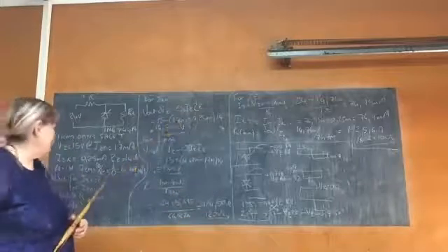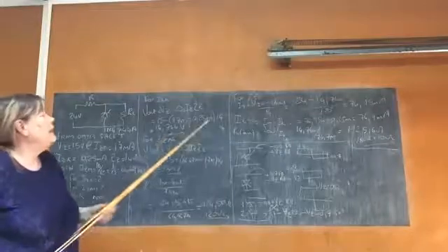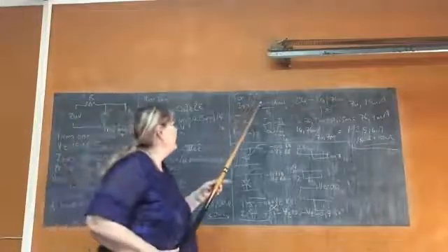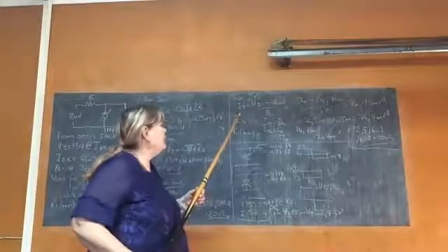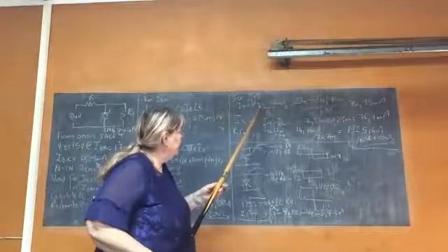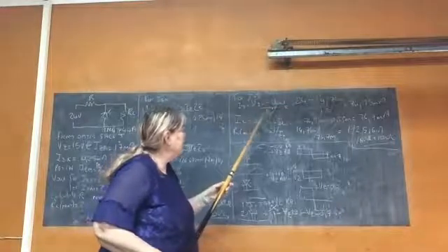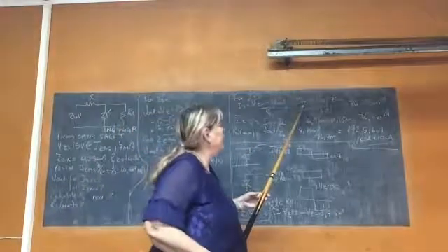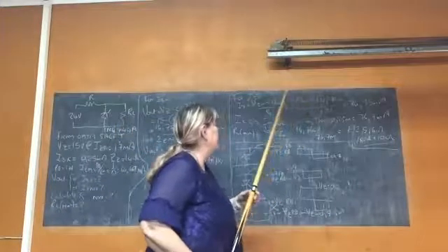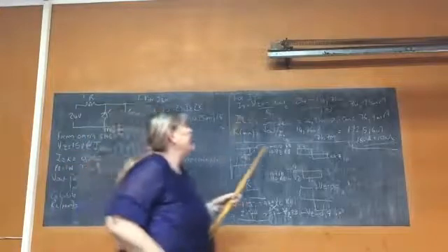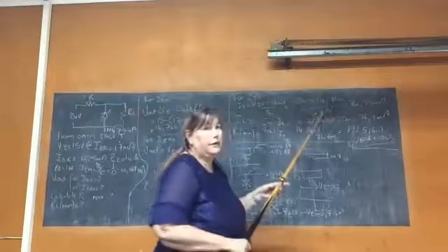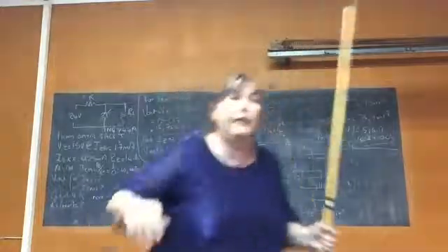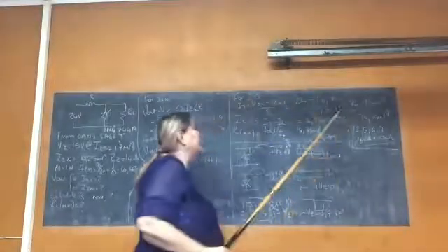Now I must determine the minimum. So for my minimum current, I can determine my I total, which is V in minus V out over R. Therefore, your 24 minus your 14.766, and over your R1, your 120 ohms, the nearest available value, and you get your answer, a total current.